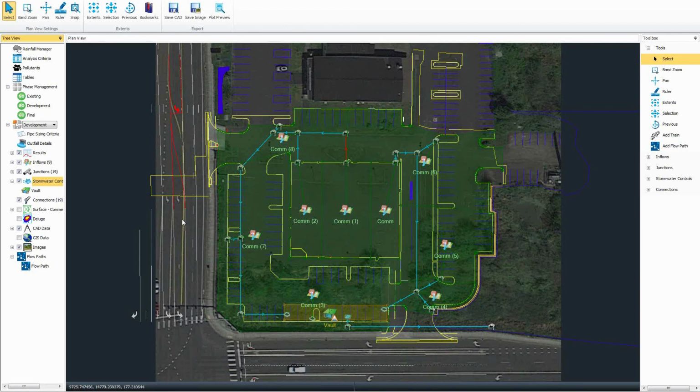So I've exported all the CAD details, all the pipe network, and all its 3D information, and exported out to GIS. Maybe just some basic reports, right? Maybe your drainage report. Now that the civil team, the site team is satisfied, they have all the details to finish that final grading.